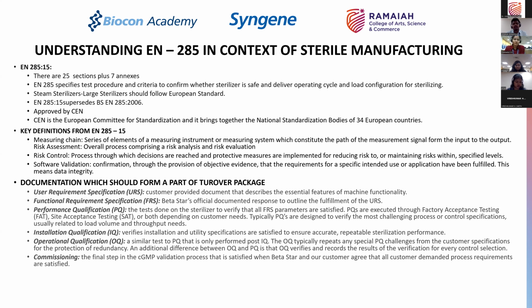Okay, what are the software functions that he is going to add into it so that it meets the data integrity requirements, the CFR 21 Part 11 compliance, the requirements of GAMP 5, etc. So the DQ is an important document which is given by the vendor so that you, as a user, can evaluate that the vendor is designing and manufacturing the equipment as per your URS, and this is to be signed off. Only after you sign off a DQ does the manufacturer actually start construction of the equipment.